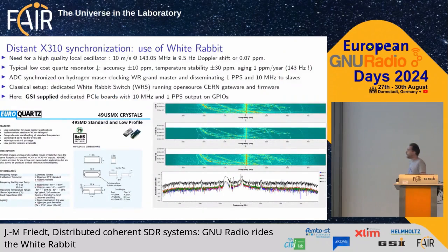So now that we have all this data, here is a typical measurement. These are 3 of the 4 antennas I put on the roof. And because you're only 40 kilometers from a 400 kilowatt radar, you just put a monopole on the roof, and that's enough to get the signal. Now, you have here all the tracks. These are waterfall plots, sorry. This is the frequency, this is the time. And as I told you, the frequency in the GRAVES radar happens to be equal to the velocity in meters per second. And these arctangent functions are actually the projection of the straight flying plane on the baseline between the emitter and receiver.